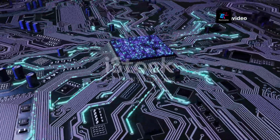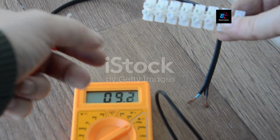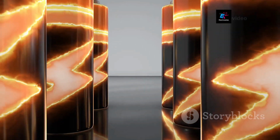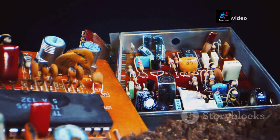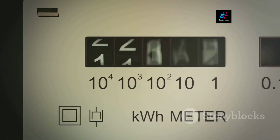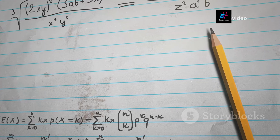Section 7. Putting it all together: how these concepts work together. So we've learned about voltage, current, resistance, and power, but how do they all fit together? Think of it like this. Voltage is the pressure that pushes electrons. Current is the flow of electrons. Resistance is the opposition to the flow. Power is the rate at which energy is used. These four concepts are related by a famous law called Ohm's law.